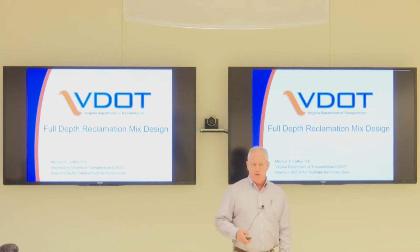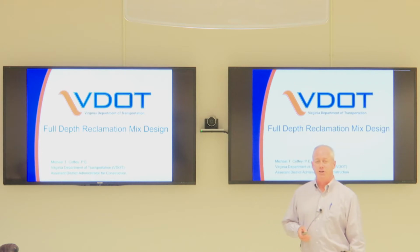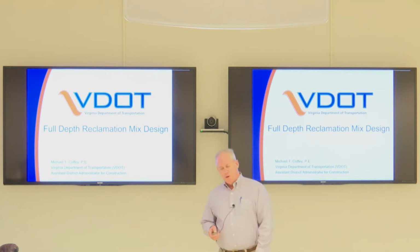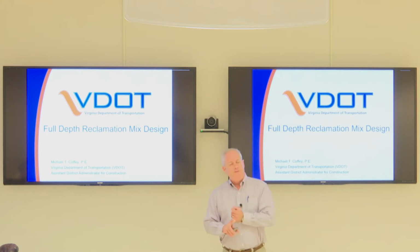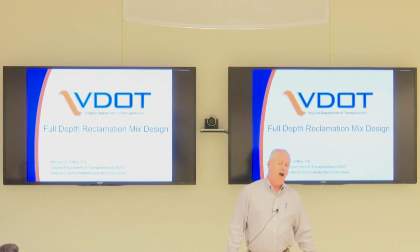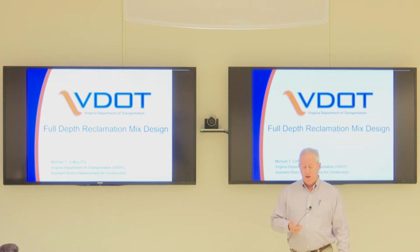I'm a VDOT district construction engineer in Fredericksburg, but I've got a long history with full depth reclamation, and in particular, the mix design. So in the VDOT world, we generally, before the contract is advertised, determine the depth of reclamation and generally what type of agent we're going to use to stabilize it. Once the job's awarded, the mix design becomes the responsibility of the contractor, and they'll hire a consulting firm to sample and do a mix design. And that's our subject.